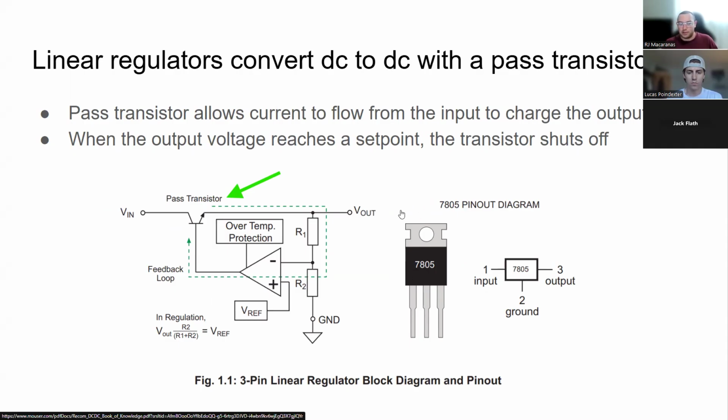output, right? And so whenever we have voltage, there's some amount of capacitance here that's actually holding the voltage up. And so by turning on this transistor, we're effectively charging up a little capacitor here to increase the voltage to some certain point. And of course, if you recall how capacitors work in general, the most voltage that can be seen at the output will be the voltage that's being applied. And if we assume that this is a perfect little switch here, then the maximum voltage that the output will see will be the input voltage.